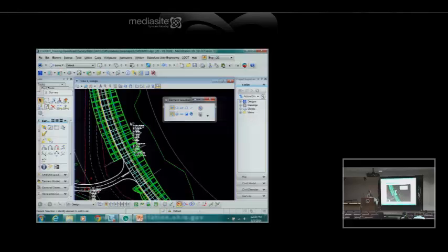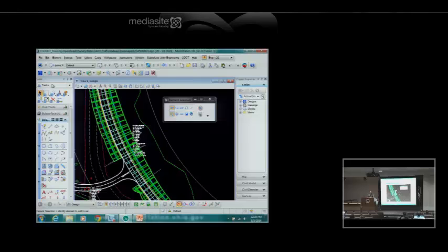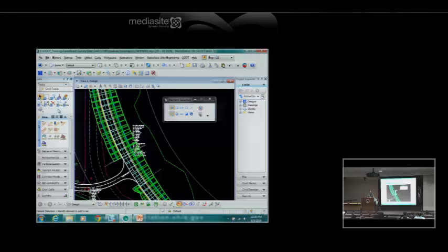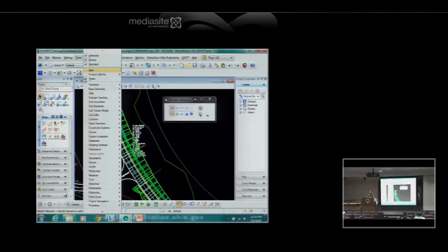But I'm not really in OpenRoads. I'm just in MicroStation GeoPak. And the OpenRoads tools are embedded in task navigation. So in my task list, there's a group of civil tools, and that's where I'm going to find the OpenRoads tools. It's also in tools. They're scattered throughout here. I never use these pull-downs to access tools, but you can find them there. You can dock tool palettes if you're into that and stuff.